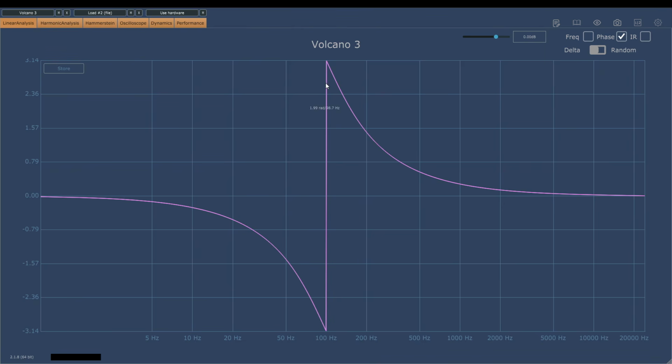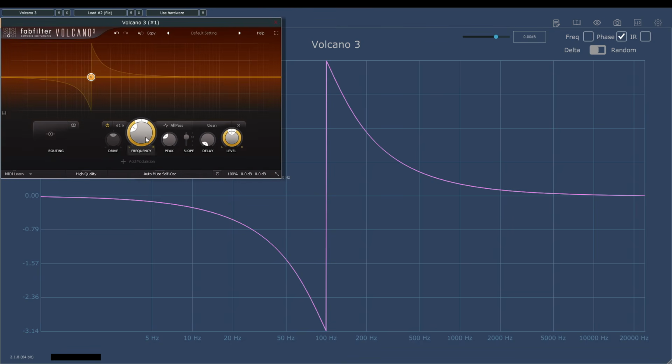This actually represents 180 degrees phase shift, and it isn't really a discontinuity at all. In fact, the phase smoothly rotates through 180 degrees and back round the other side of the phase circle. But because of the way we're representing that on the graph, the line disappears off the top and reappears at the bottom again. But it's quite useful, really. That vertical line shows us precisely which frequency will be rotated by exactly 180 degrees, and we can confirm that it is indeed exactly the frequency we've set for the filter cutoff.